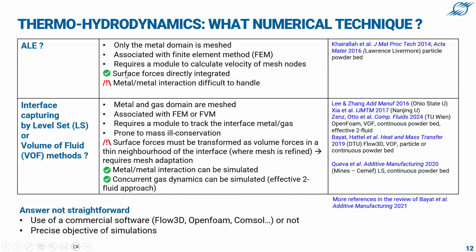What is nice is that surface forces can be directly integrated because you can integrate on the surface of the mesh, which is the surface of the material. And this is not the case for VOF or level set formulations. In this case, the surface forces must be transformed as volume forces in the neighborhood of the interface in order to be taken into account.